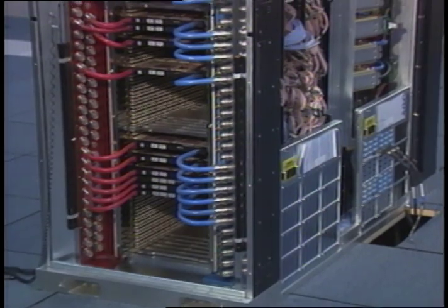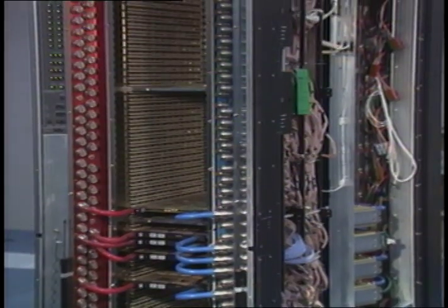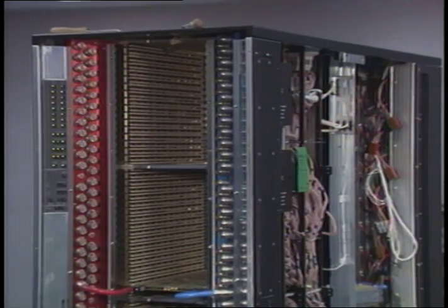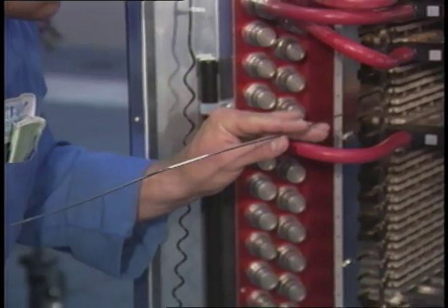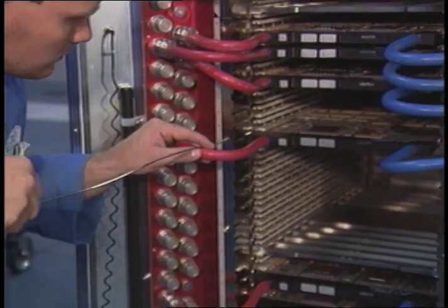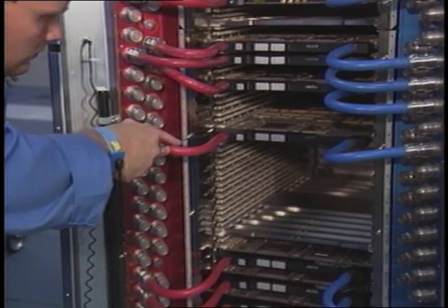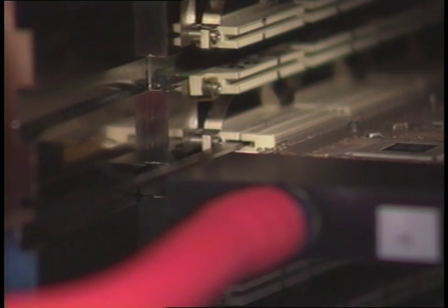A single CRAY T3D chassis can support up to 512 compute processors, 8 I/O gateways, and additional redundant processors for fault tolerance. The zero insertion force connector is activated and deactivated by inserting a cam down each edge of the module after it has been inserted in the module slot. The cam works to move small sliding contacts one by one out of the chassis-mounted connector half of the mated pair into the half mounted on the module.